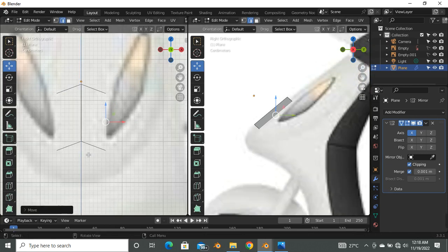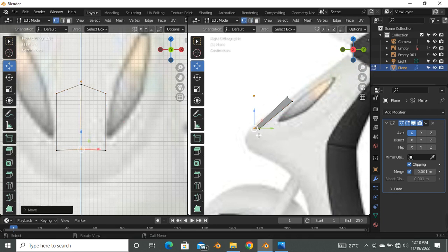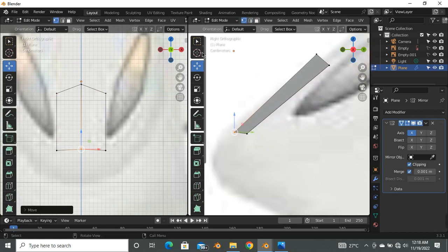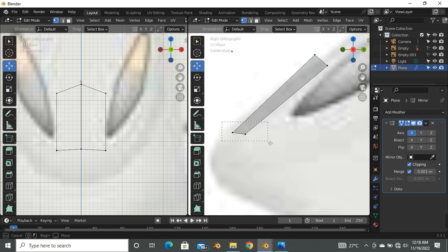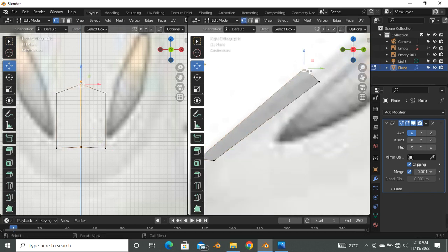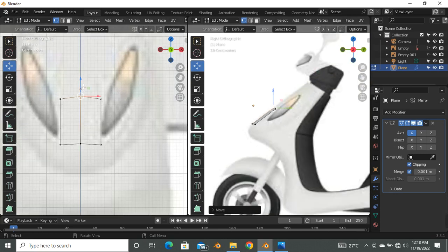As we are beginners, I would say 1 for my vertex selection. Select these vertices and I'll just push this downwards. I can come to this place also and say Alt Z also, so I can activate my wireframe in this view also. So I can now push these vertices. So I'm just creating my starting point first before I start modeling. And I can bring this guy downwards.